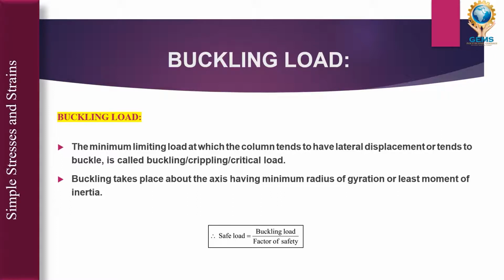So if you see one more thing, what is safe load? Safe load is equal to buckling load divided by factor of safety. Sometimes in your examination they will ask this point in your numerical, what is safe load? Because whatever we design in engineering mechanics or in mechanics of solids, we must know what is the safe load for any strut or for any column, for any structural member.